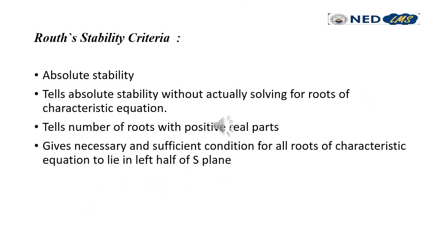It also tells us the number of roots with positive real parts. Actually, roots with positive real parts cause instability in the system. So it tells us the number of roots with positive real parts which are causing the system to be unstable. This method gives a necessary and sufficient condition for all roots of the characteristic equation to lie in the left half of the S-plane.